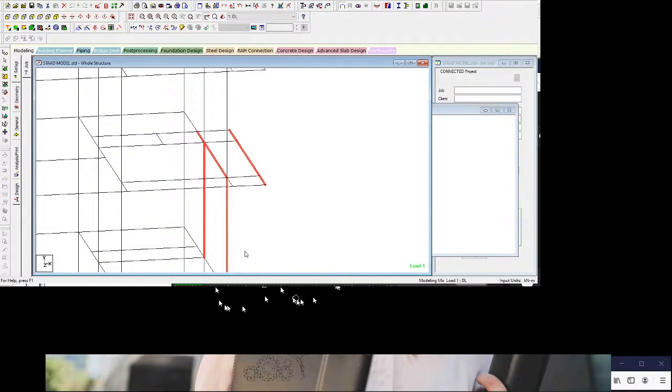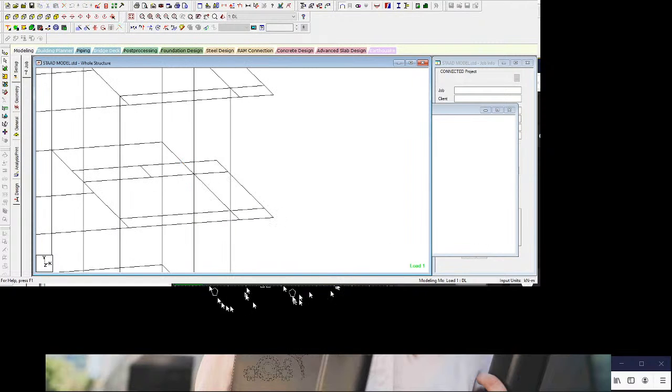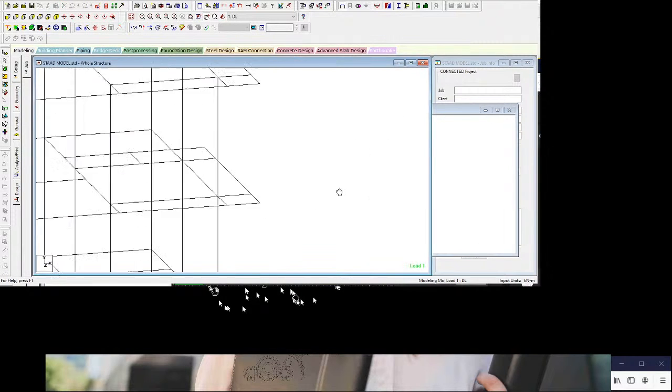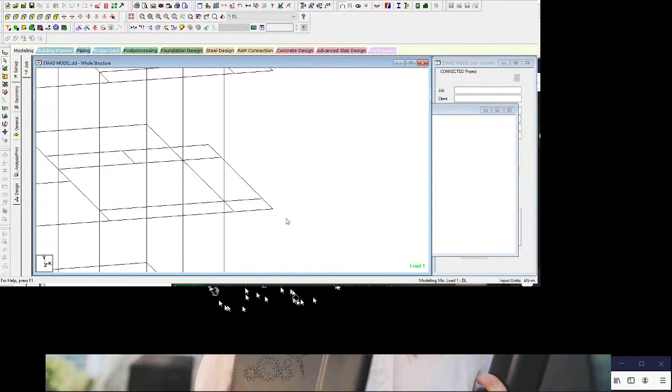But in this condition, it depends on the cantilever. You can see here a 0.9 meter cantilever, and some twisting moment is also generated. Then you should provide only some light load here. Don't provide a higher load. You can provide a 4-inch wall or balconies, and definitely the load will be distributed to the next beam.